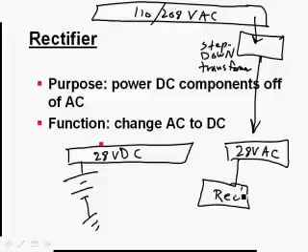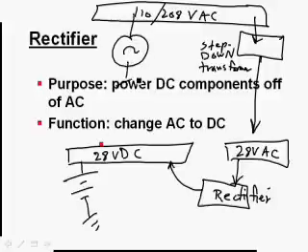we have a rectifier that gets fed off of alternating current and turns it into DC. Now we can charge the battery, so we can have our big AC generator that runs the main bus bar. We can step it down, and now we can have lower voltage alternating current if we need it, and we can also change that low voltage alternating current with the rectifier into low voltage DC and run that.